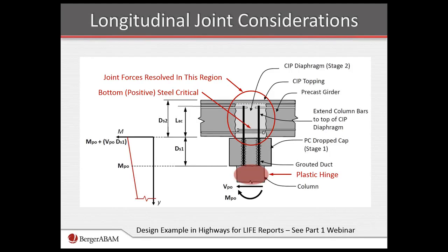transition from the forces in the vertical steel coming out of the column and the cap beam to the horizontal steel that's in the girders and topping. So, for example, precast pre-stressed girders, we'd have strand or some deformed bars, but strand also extended out of the girder, so you'd have strand chucks, for example, in place. You need overlap between those to be able to develop the strength of the girders in positive moment.